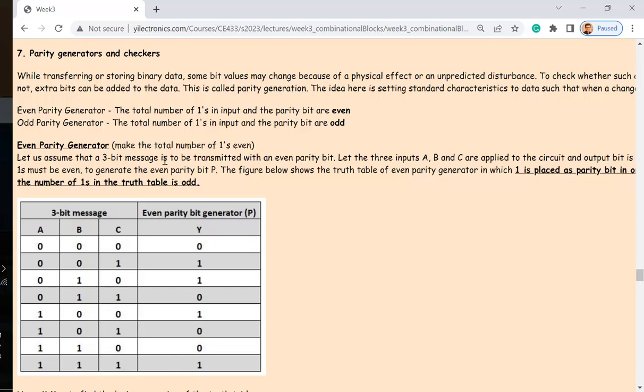How could you make sure there is an even number of ones in those bits? Because digital data can be all different, depending on the data, like a temperature sensor sensing temperature data. It can be all different. But there are only 2 possibilities, even or odd number of logic ones. So we have an agreement that we are sending an even number of ones over to here.